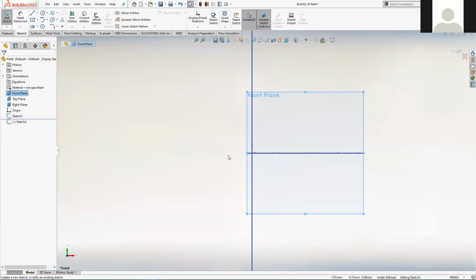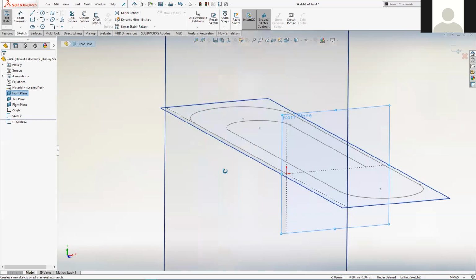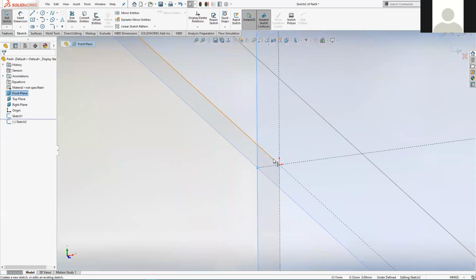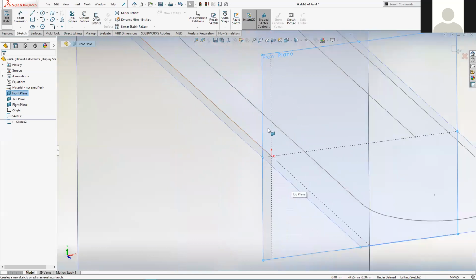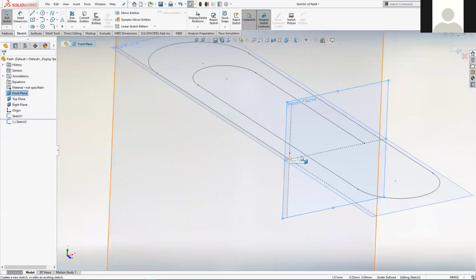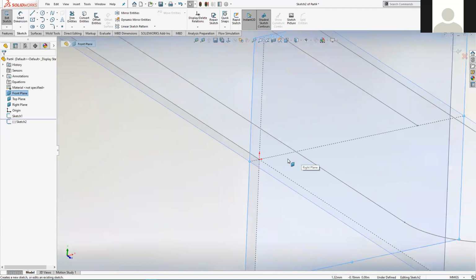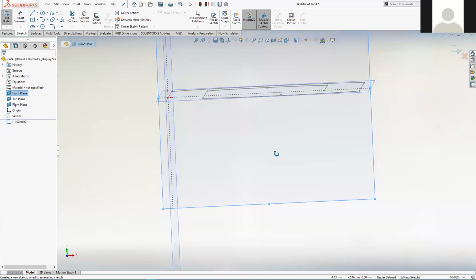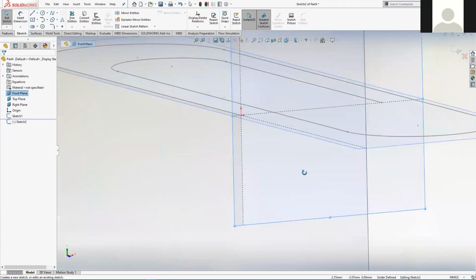And then because of what we're trying to achieve here, we're trying to create, in this case, a circular shape that is centered around the end of our first sketch. So it's centered around that line. And that's the reason I've rotated my view to more of an isometric viewpoint, because it's easier to see that relationship if you're not looking straight on at the line like that.